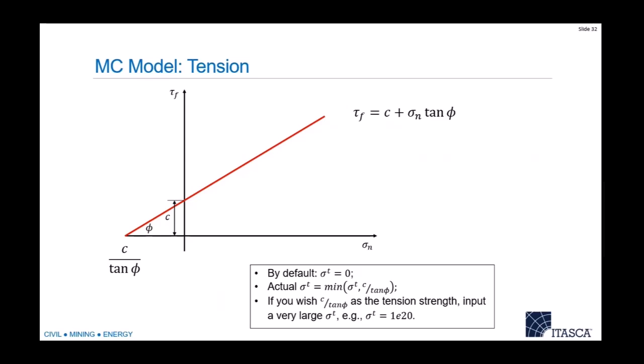This is the tension that I already talked about. If you guys have used RocScience or FLAC or Midas or whatever, most of them do an implicit solution. And what happens with these programs is they take a big step and they go past the line here, and they have to do a correction and come back down to the line. So they do this sort of iteration. We don't really do that because we're in the explicit world. We get here and we might go a tiny bit over, but it doesn't really matter. The next step is along the line and along the line and along. So we don't have to do these corrections in the same way that they do in the implicit world. It just progresses and follows the line.